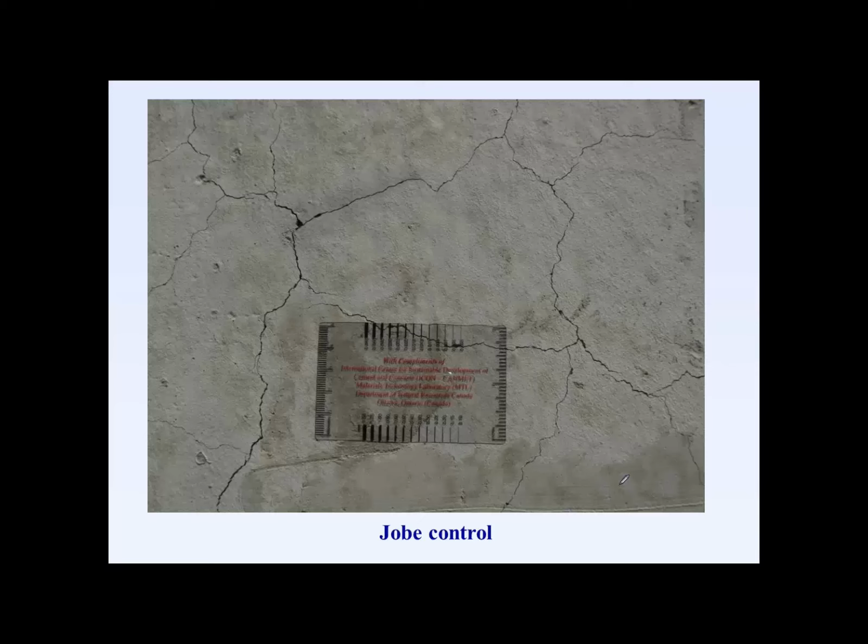Now, one of the things we also did as part of the study is we wanted to look at, hypothetically, what could we do in terms of getting lithium into concrete, and looking at a best case scenario. What we did is we cast 3 concrete blocks and stored them outdoors. The first one is shown here. All 3 blocks were identical. They all had a highly reactive sand from Texas, and they all had a very high alkali content.